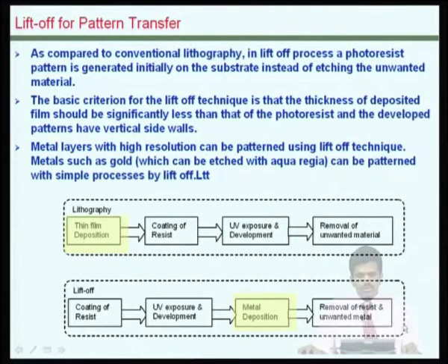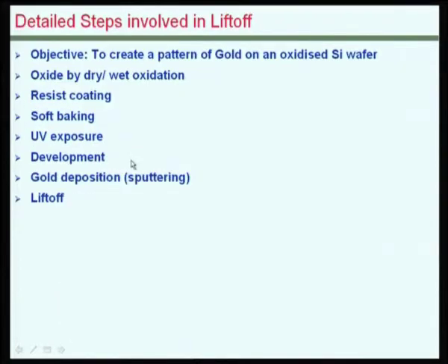So, when the resist is removed, the unwanted metal will go, and we will see that soon. So, with Liftoff technique, we can get high resolution geometries patterned, and as I mentioned, it is typically used for gold layers.